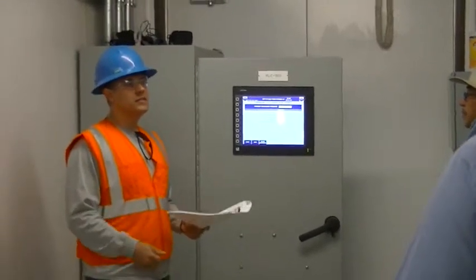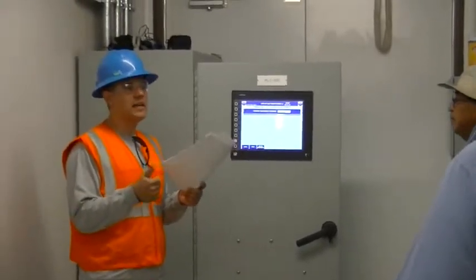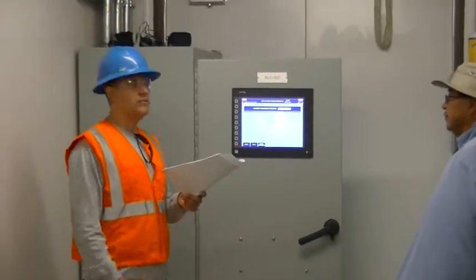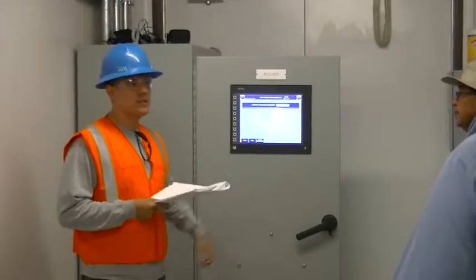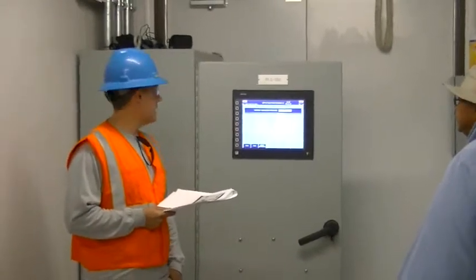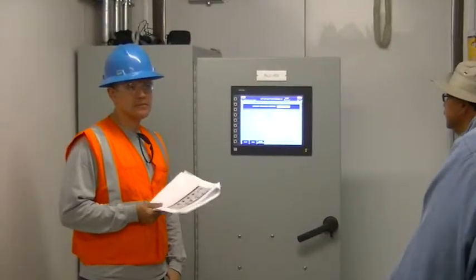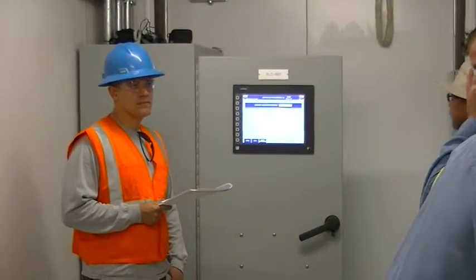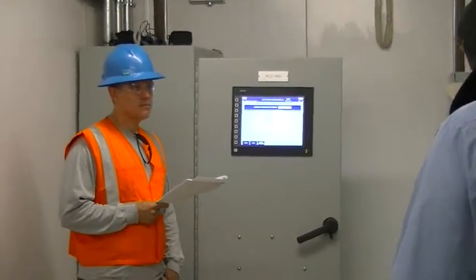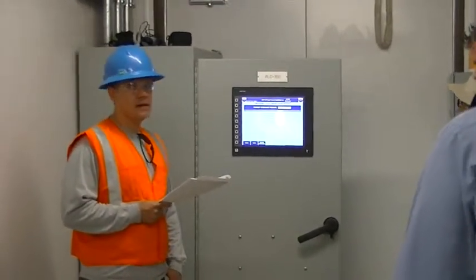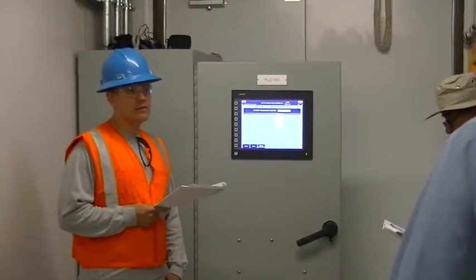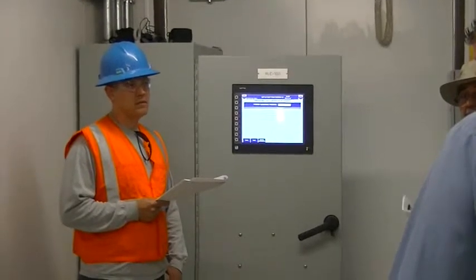So those VFDs should be on, trying to maintain that. If they cannot maintain 65 PSI, say you've got a lot of water being released and we have to bring those on, that's when that occurs. So probably, if we put it in auto, the way our system is running right now, those would probably never kick on. No, unless we get a big leak. Right. Yeah. Okay, but is there a way that we can periodically just run them?